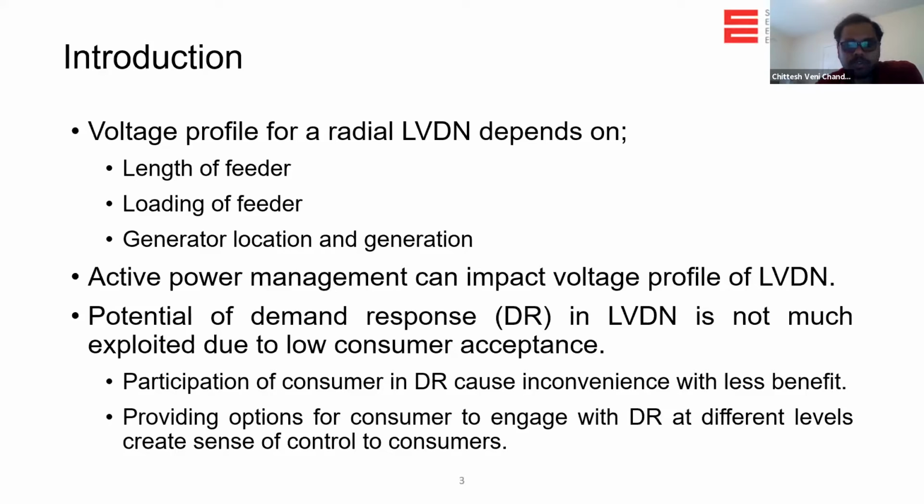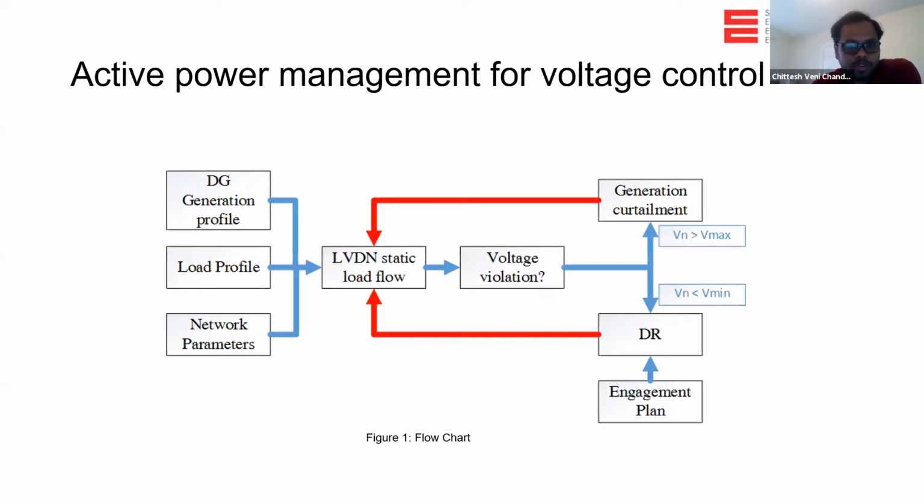So we wanted to give options for the consumers to choose from, to decide on the amount of participation in the load reduction. So we allocated different consumer engagement plans. Moving forward, what we wanted to do was manage the over voltage by generation curtailment and the under voltage by a demand response program.